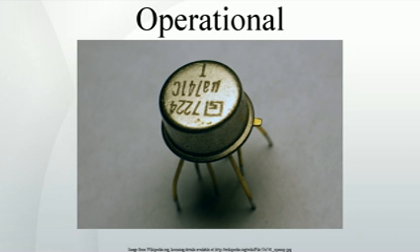Applications without using any feedback. That is, the op-amp is being used as a voltage comparator. Note that a device designed primarily as a comparator may be better if, for instance, speed is important or a wide range of input voltages may be found, since such devices can quickly recover from full on or full off saturated states. A voltage level detector can be obtained if a reference voltage V_REF is applied to one of the op-amp's inputs. This means that the op-amp is set up as a comparator to detect a positive voltage.